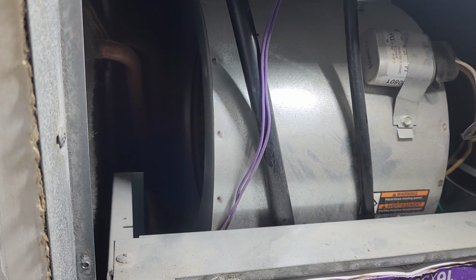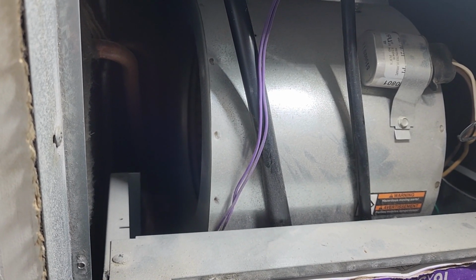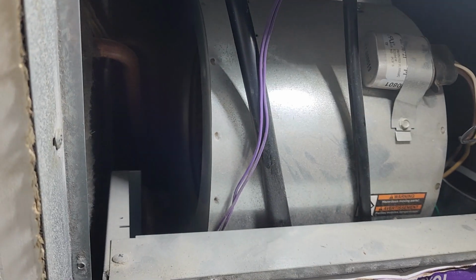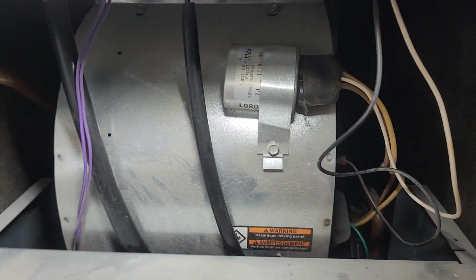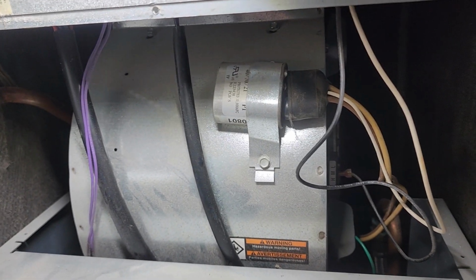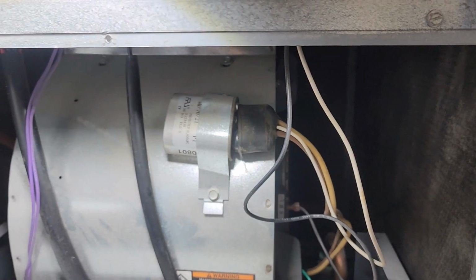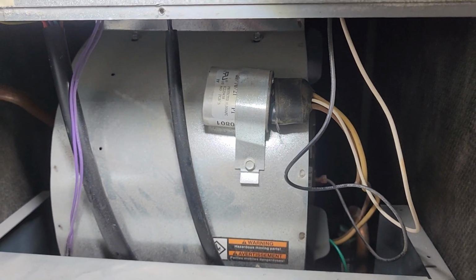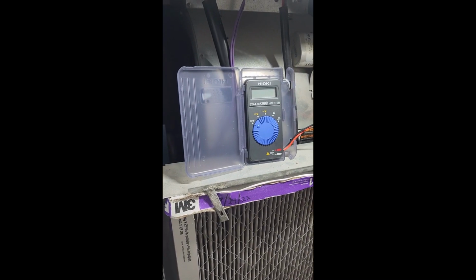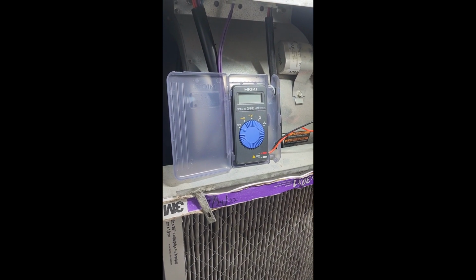So we're first going to try to turn the fan over by hand. And if it spins easily, which means that there's no issue with anything being stuck in it or with the bearings worn out, we're going to start testing some voltages. So we're going to look at that start capacitor, and looks like some connectors to the actual fan itself. So let's continue.